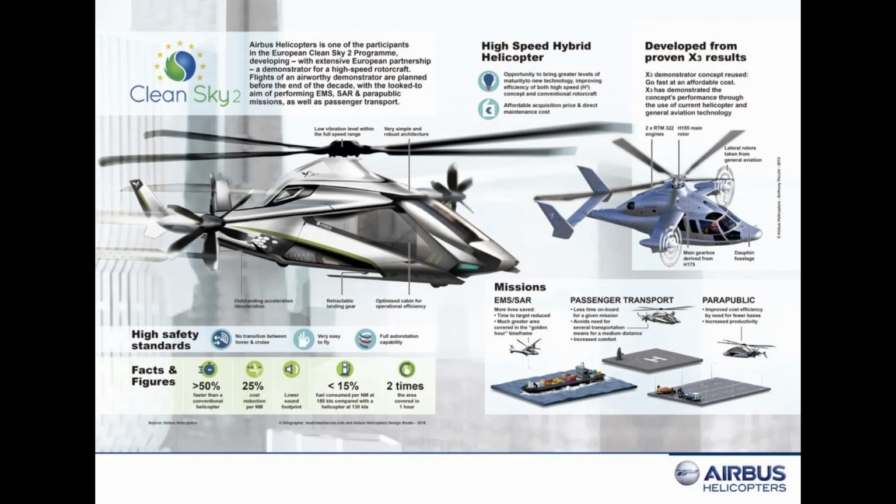Special attention should be paid to ensuring that all seatbelt cushions and any other loose items are stored away to prevent ingestion into the main or tail rotor. When reattaching the doors, proper care must be taken to ensure that they are fully secured and closed.